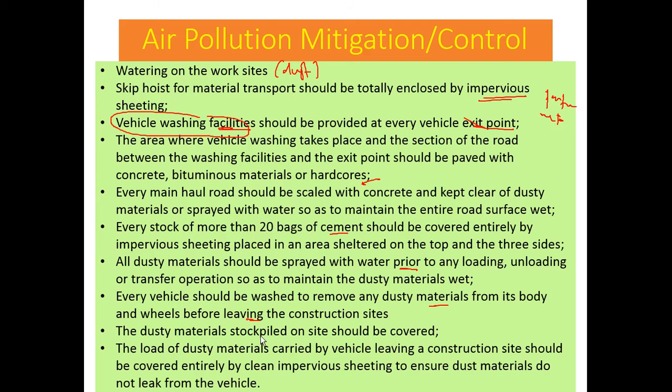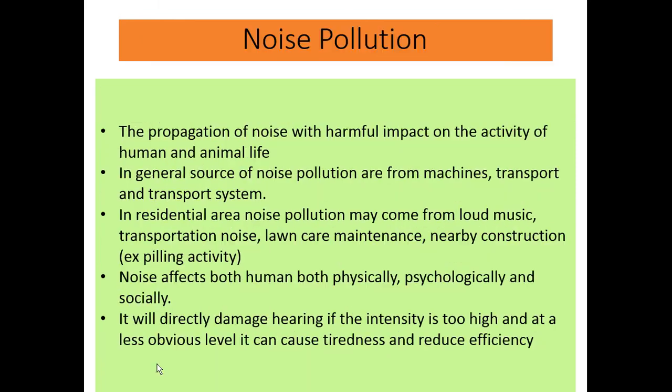Dust material stockpile on site should be covered. Okay, for any sources of particulate matter we need to cover. Let's say this: skip hoists for material transport covered, stockpile covered, loose dust material on construction vehicles should be covered, automatically covered, to avoid particulate emission to the air.